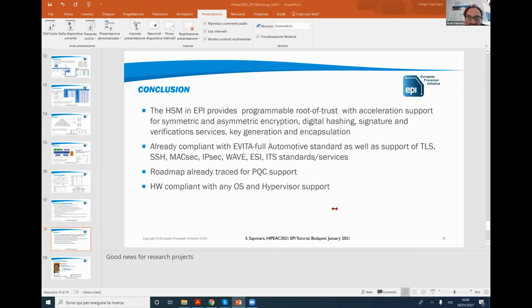Okay, so I will try to resume. I see some question about the use of the RISC-V. Okay, as I said, for the moment here, the RISC-V is used as a programmable part to ensure compatibility, backward compatibility. For example, SHA-1 is not supported, but this can be run via software on an Ariane 64. So for the moment, the RISC-V is not a modified RISC-V, it is taken as is, the Ariane, to give programmability.